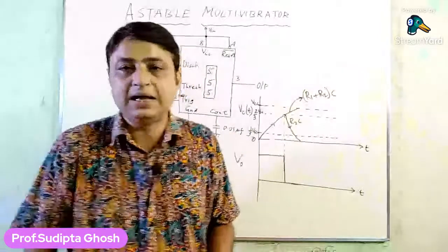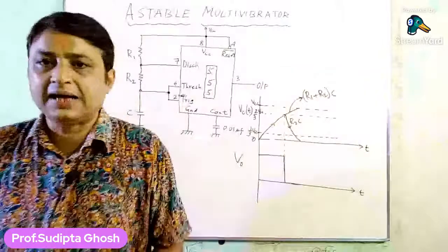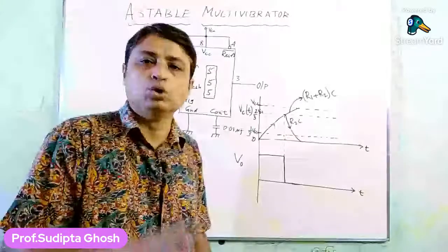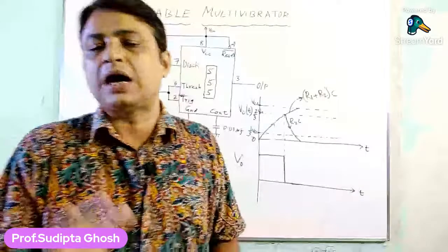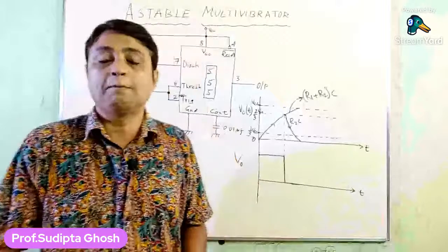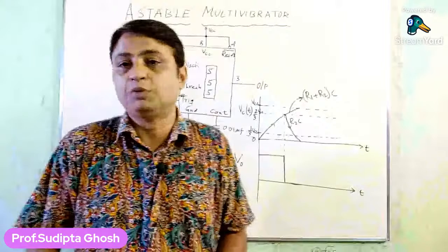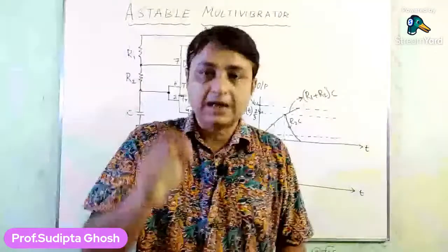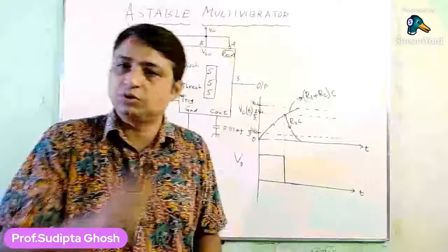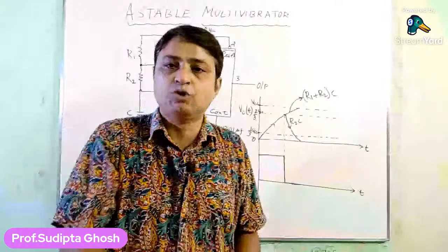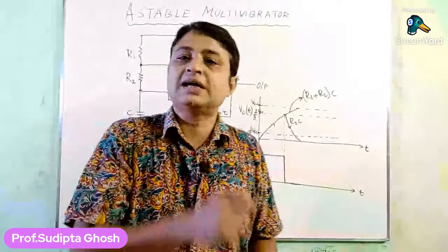It will act as before. That is, as the value of the trigger input goes below 1/3 VCC, it will again make the output of the trigger comparator go high, and as the trigger comparator output is connected to the set input of the SR flip-flop, it will make the SR flip-flop output, that is Q of the SR flip-flop, go high.